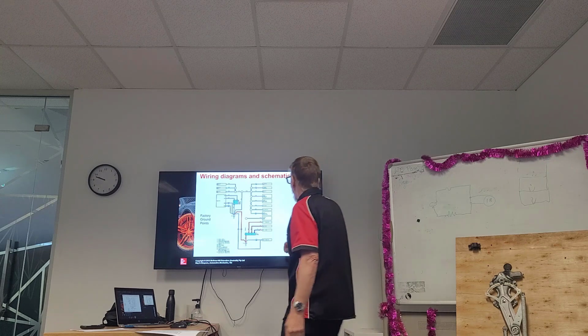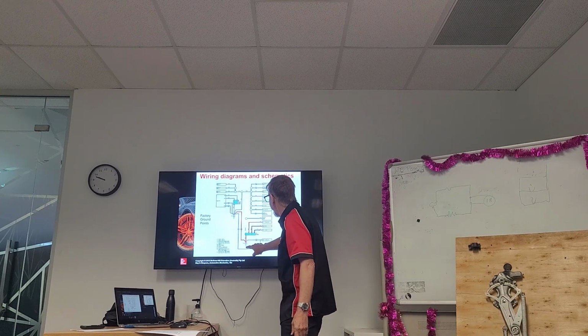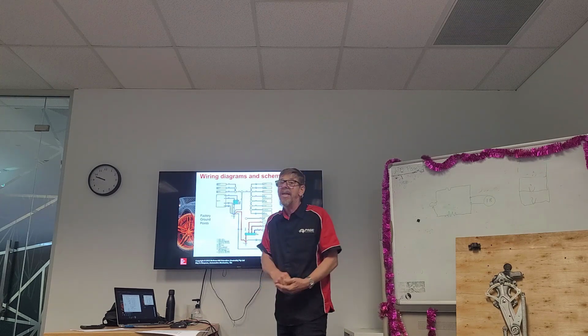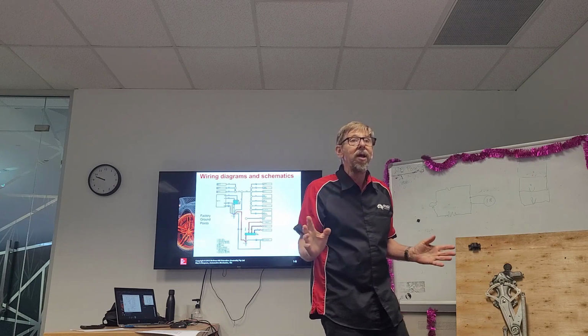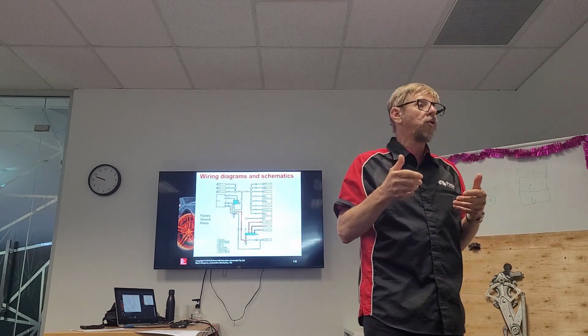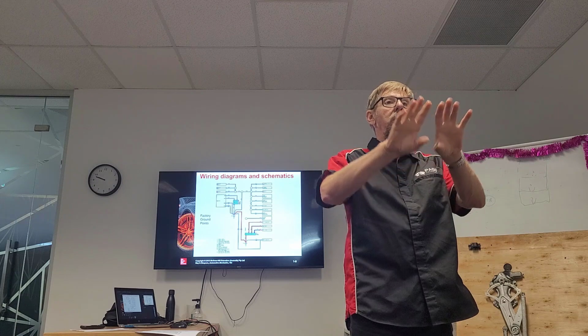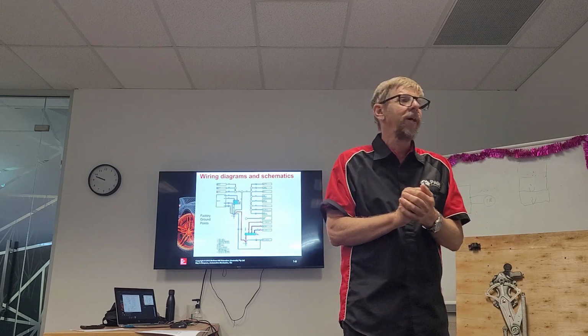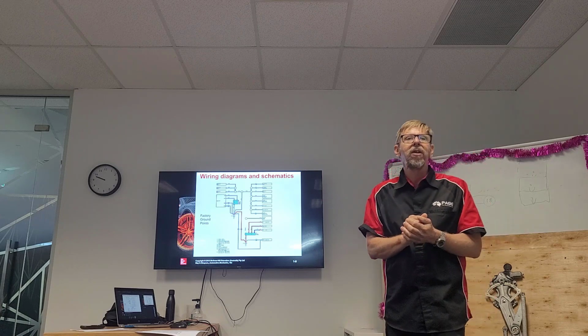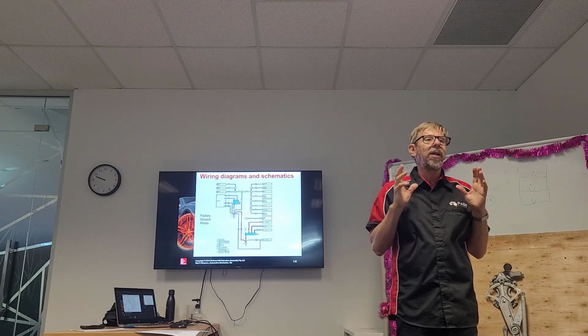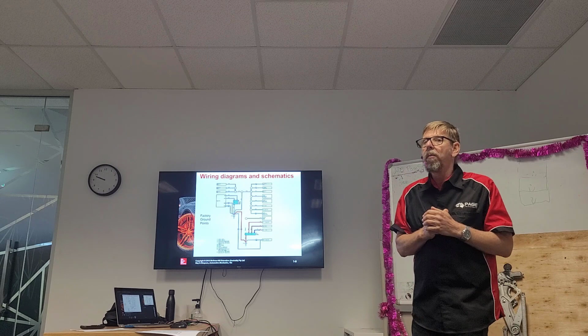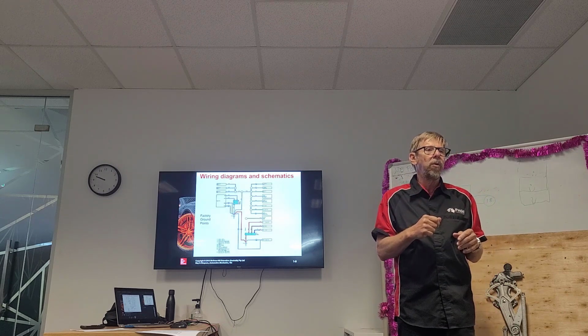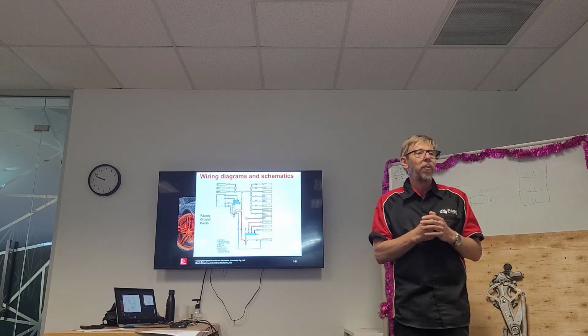And then from that one point, it then goes to this ground point. And it's got a symbol of ED. I don't know where ED is, but we'll go to another section in the workshop manual, and it'll show you on an exploded view the position of ED, which is a ground point, okay? So that sort of information is necessary for us to be able to possibly locate these points where we could have a bad ground somewhere, okay?